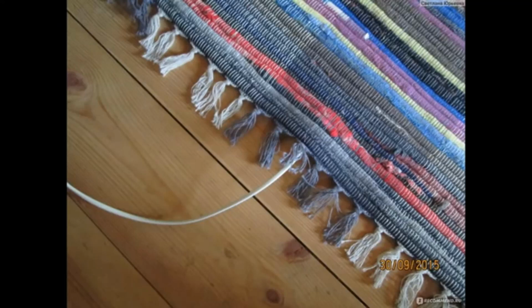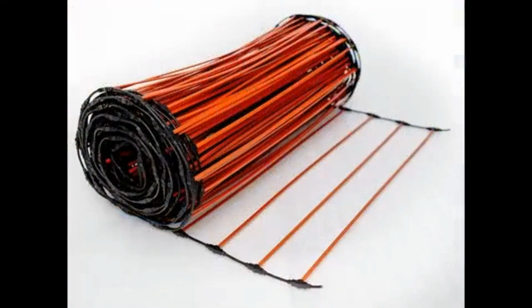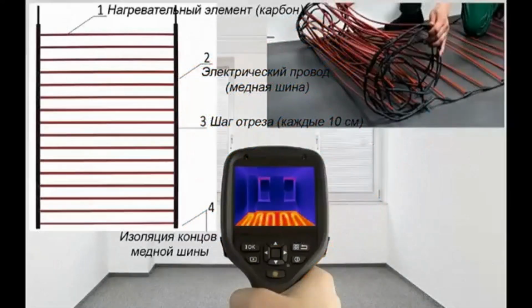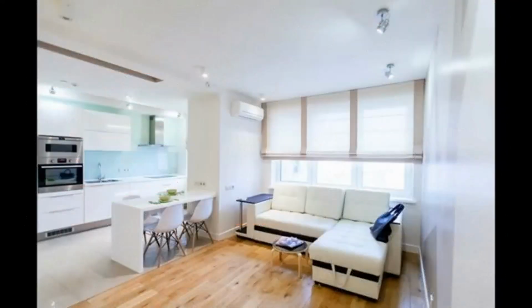Next, a more advanced infrared floor heating system: rod infrared heating. This system appeared as a hybrid of cable floor and film solutions. Its main heating element is carbon rods, which, when energized, emit infrared heat range. It is also called intelligent electric floor heating. Benefits: you can easily put furniture on it since it is not afraid of overheating and is self-regulating, compatible with all types of coatings. It can be poured under the screed. Eco-friendly: there are no spurious emissions.